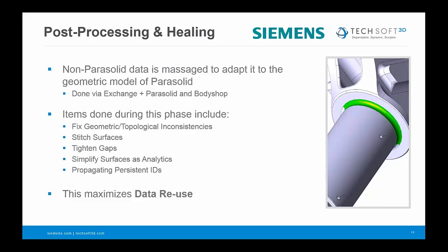So the first thing, and Jonathan showed it, when you read in the CATIA file, you'll notice that the canonical forms of the geometry are maintained. All these systems have support for these canonical forms. So when you're talking about conical, spherical or planar surfaces, all those we bring over and maintain in their original form. Then when you get to some of these advanced free-form surfaces, you do need to adapt the data. And so that's where we do some work.